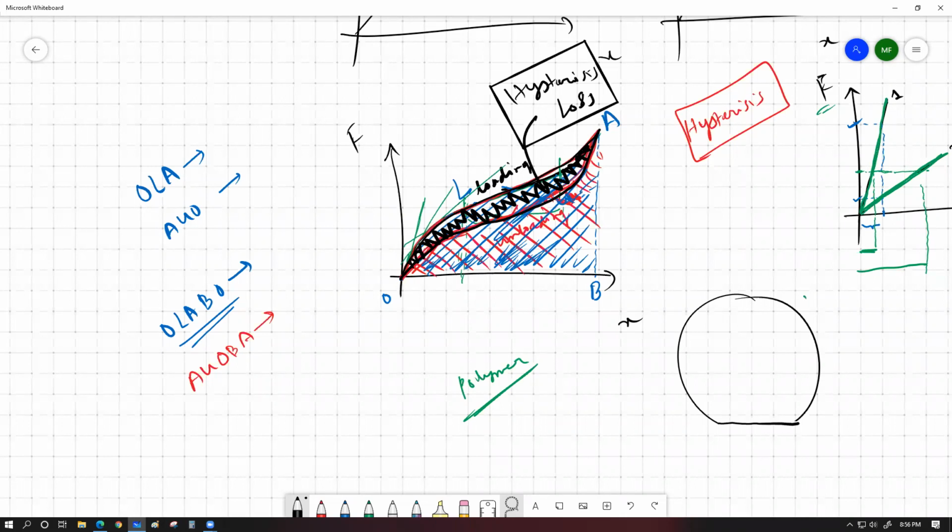Sometimes heat of the tire is also needed, also expected, for better gripping capability of the wheels, which is a very important aspect for Formula One racing, for which they use slick tires with no grooves in them. But there is much more technology for that. But bottom line, do you understand the idea of the hysteresis loss?